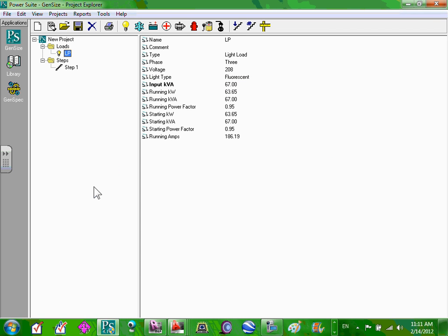My friends, you have just assigned a lighting panel to be powered by your generator. Can I have thumbs up? Good. Let's go to a receptacle panel. Okay, receptacle. Look at the loads that we have here. Can you guys see that little guy here? Look at my options. My options are light, air conditioning. Receptacle is not air conditioning. Battery. I have medical. I have motors. I have fire pump. I have UPS. The only option I have for receptacle is under miscellaneous.